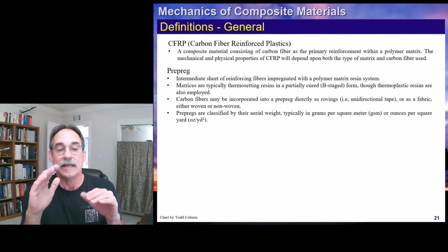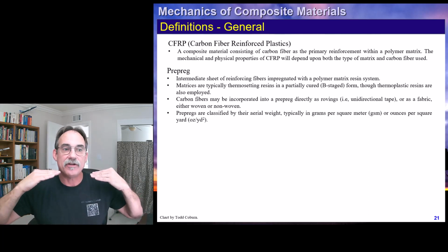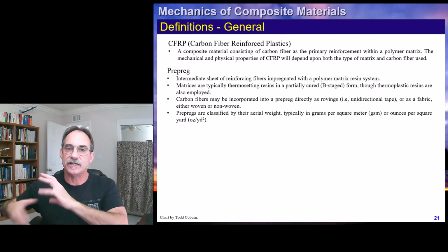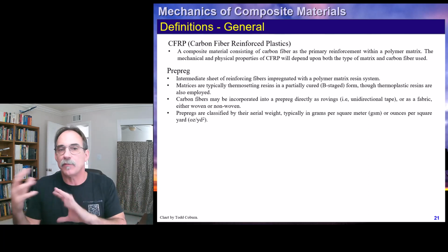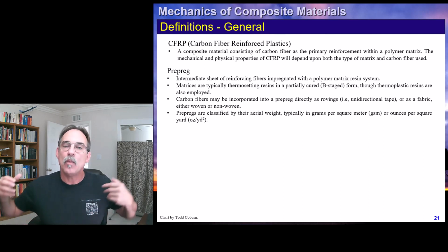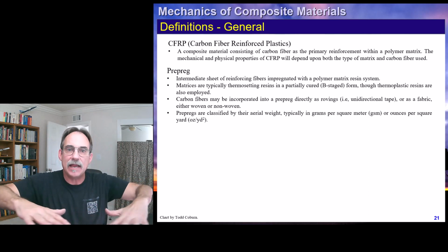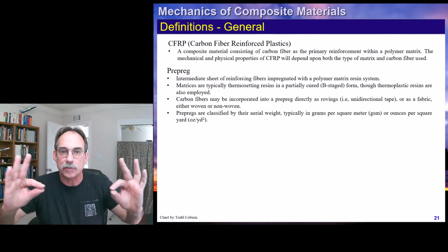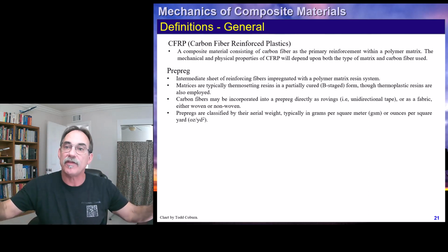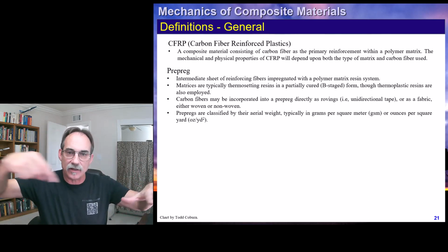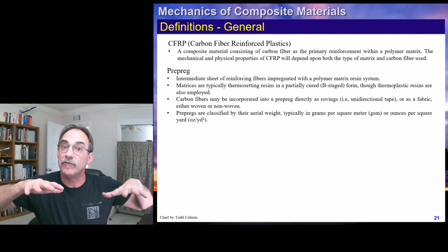We went out to their plant, and what they do is they'll often use a thin sheet of paper, and they will mix up the resin so it's nice and uniform with exactly the properties they need. Then they will take it out and drop it onto the sheet of paper that will roll out until they get a nice, precise, measured, uniform thickness all the way across. And everywhere they're checking the thickness to make sure it's all uniform.